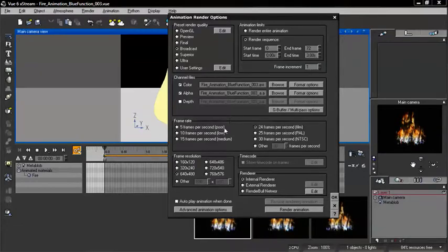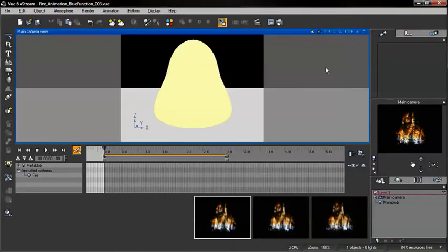And there's a couple other things too before we go ahead and render this. Now this scene's already set up specifically for this type of render. I'm just going to click OK for right now. But we have that black background loaded in with no ground plane. Now it's important when we're rendering that the only thing we're rendering is just the fire itself. If we have a ground plane or any other infinite plane or any other object, it's going to affect our alpha. If you've already set up a scene and you have infinite planes or any other objects that you'd like to keep,